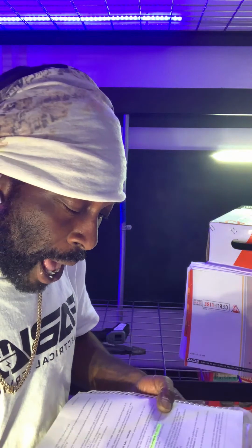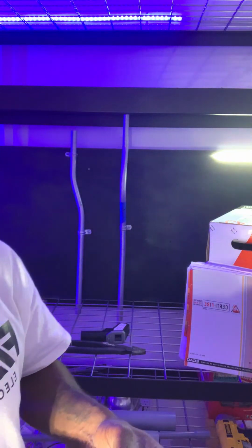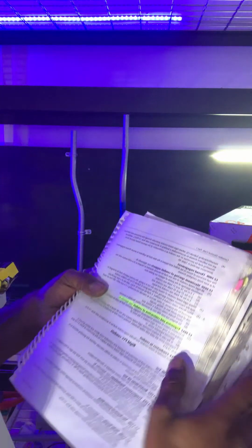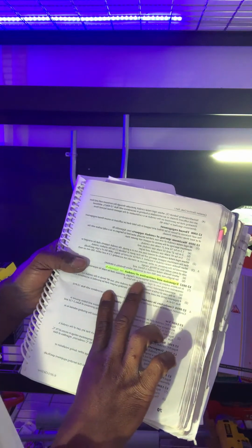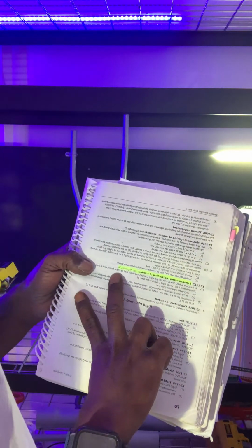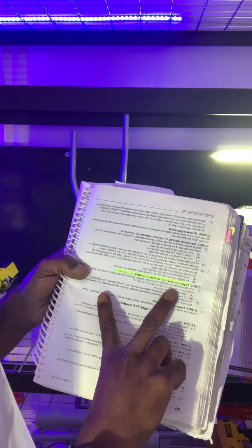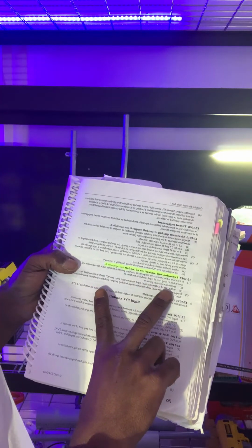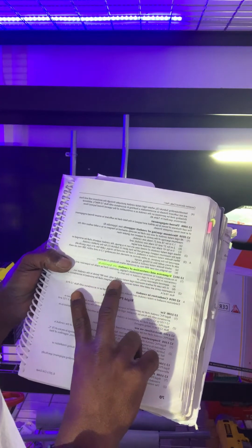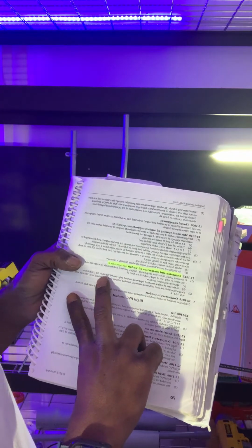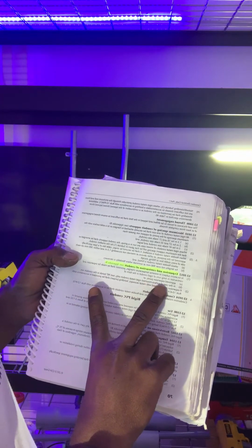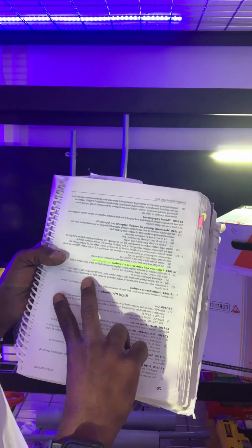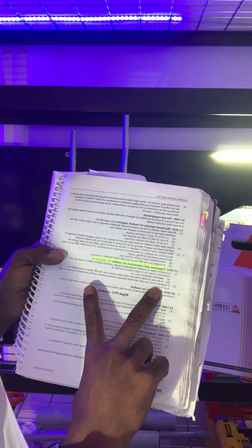Okay. You also have expansion and contraction of conduit. Tells you to see Appendix B. In locations subject to extreme temperature changes, provision shall be made for expansion and contraction in long runs of rigid conduit in the form of approved expansion joints, or in the case of surface-mounted rigid metal conduit only, bends in the conduit run. If expansion joints are used with metal raceway, bonding jumpers shall be provided in accordance with Rule 10-614.